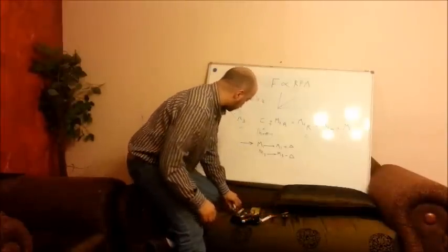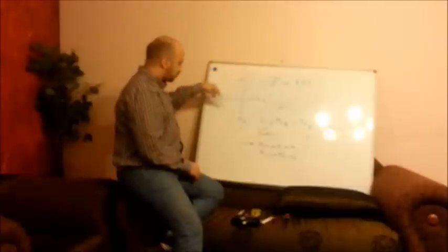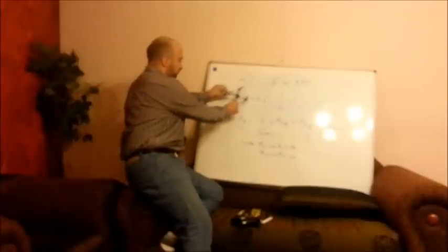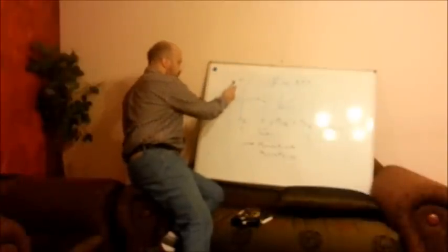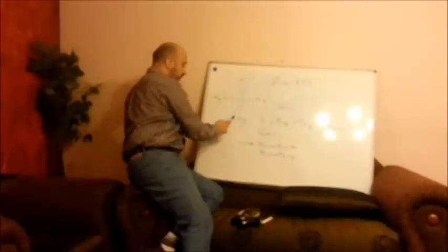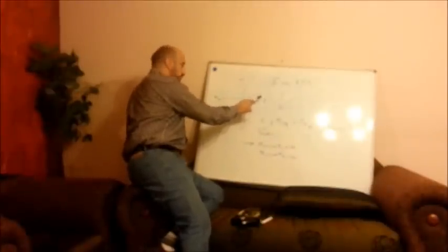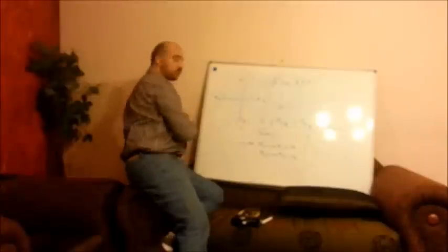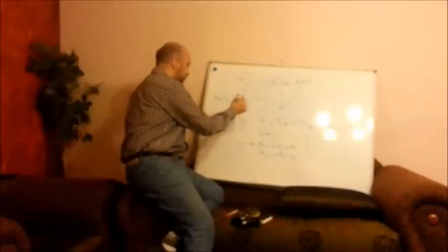So let's go back to this diagram. If I want the quadcopter to rotate, I can increase the RPM of motor 1 and motor 3 and decrease the RPM of motor 2 and motor 4. Let us study what will happen if I do that.